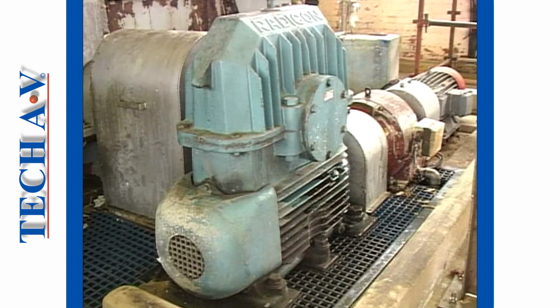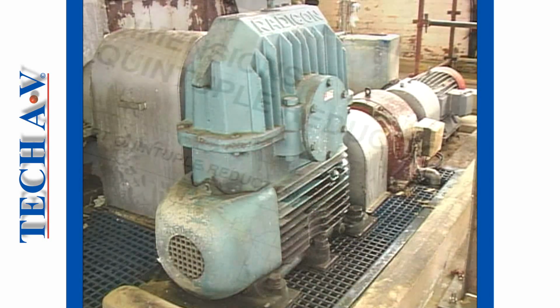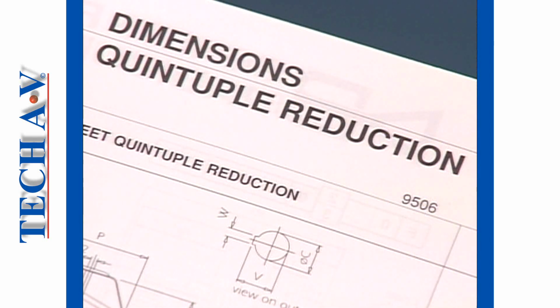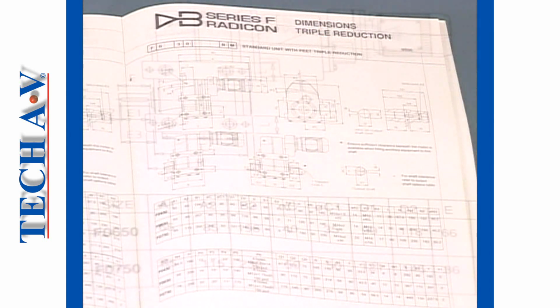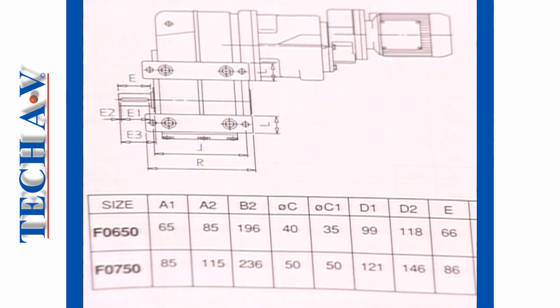Some sizes are given in a unit's kilowatt capacity, usually referring to the rated output of the reducer when driven by the recommended motor. There are no set rules about how size is determined. Most often you will have to refer to the various gear manufacturers' data for this detail.